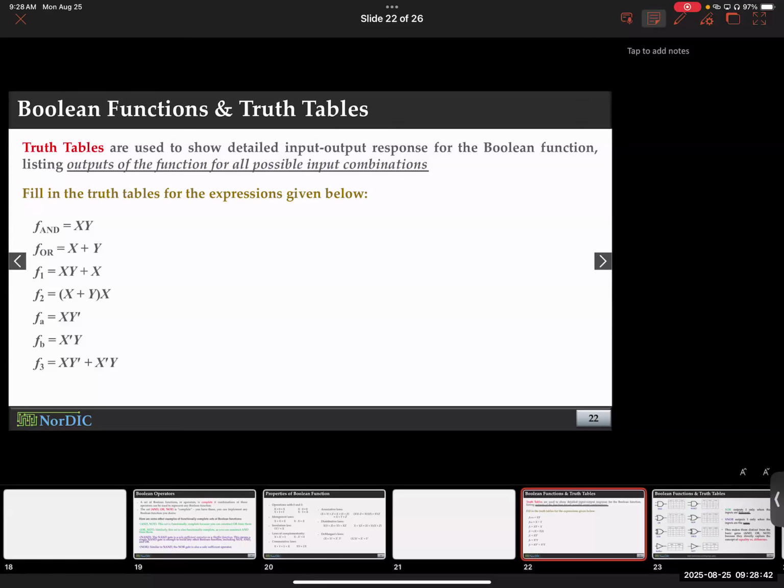We have just tried something similar, but let's do one more time, right? This is your AND function, and I'm asking you to try to create the truth table. And basically, this is AND and this is OR, and we have just discussed the truth table for AND and OR, right? Considering that we have these two in mind, can we come up with the truth table for a random function? Like, let me just take this, f2. Let's try to find the truth table for it.